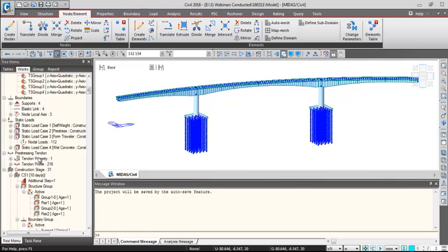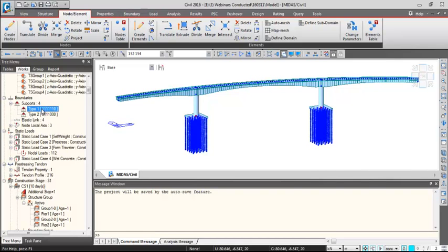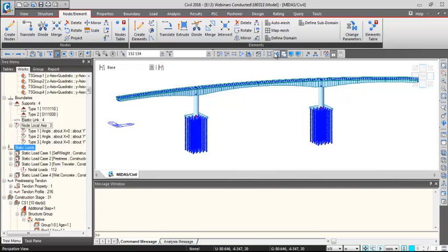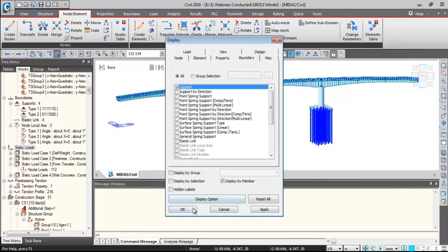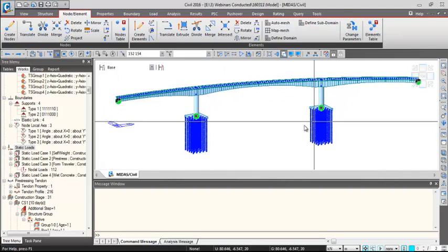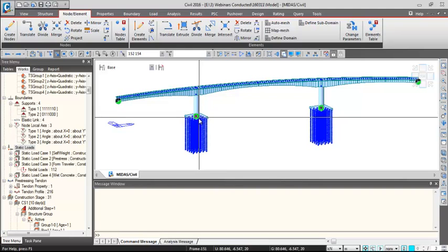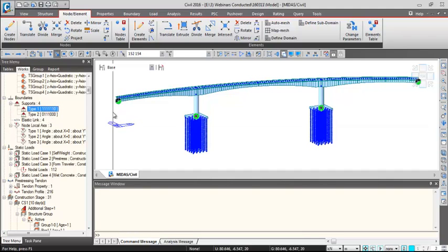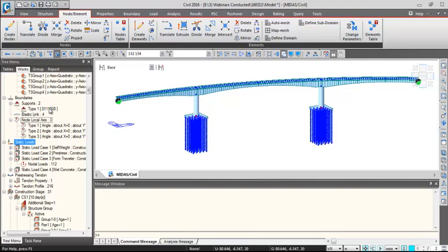So to do that, I could either do it from the table over here. Okay, so these are the supports at the pier location. I could simply remove it. So now basically if we check, I think I'll show the support conditions before I remove it so that it's clear. Okay, so right now this is the support condition. If I want to remove these supports, for these supports, all the displacements as well as all the rotations are restrained. Okay, so when we check the boundary types, type 1 has everything restrained except the warping, whereas type 2, dx is free, dy, dz and rx are restrained. Hence, dy, dz and rx are green, remaining are black. Okay, what we want to remove are the completely fixed ones, so we have to delete the type 1. Okay, and the supports there are gone.